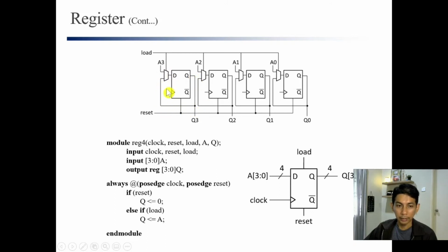All right, but you don't have to write that. The Verilog compiler will give you this line automatically. If we assume that if load equal to 0, Q should remain Q. All right, so you will get this circuit when you write like this.